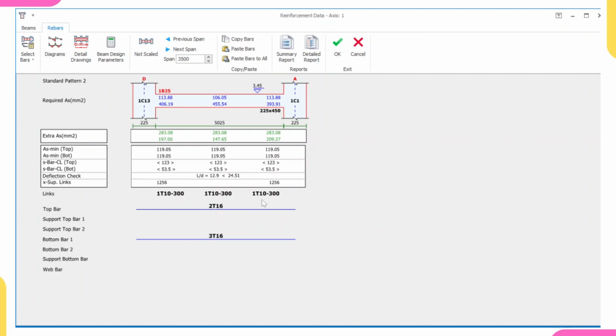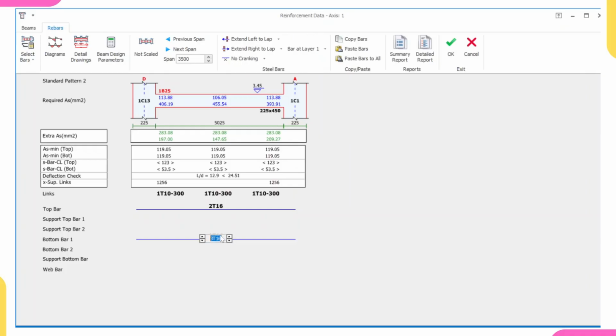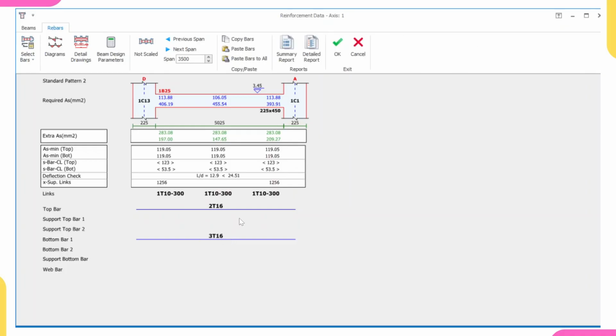And also we use the yield strength of 460. If I also go to the market, I'm sure that those reinforcements' yield strength is not up to even 437. So to counter those losses, that's why we ensure that our area of steel provided is at least 100 millimeter. It is not below 100 millimeter. If it is below 100 millimeter, please increase your reinforcement to prevent building collapse.